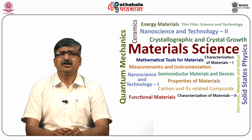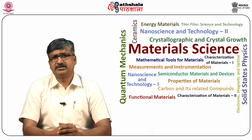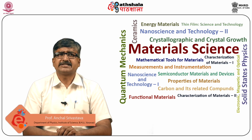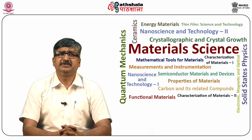The alignment of these nanotubes has been achieved with the external voltage of 6 volt, where the field is around 1888 volt per centimeter. The distribution of charges on the tube surface provides an induced dipole moment resulting in a torque. This torque is nothing but P cross E, where P is the polarization and E is the electric field. The torque aligns the tube in the direction of the field. Thank you.